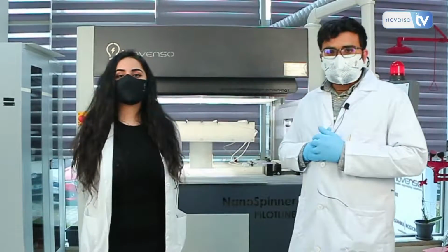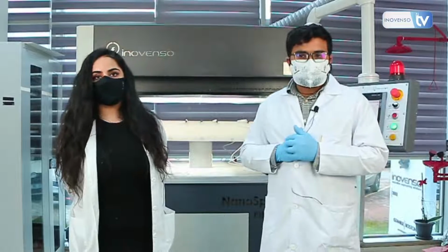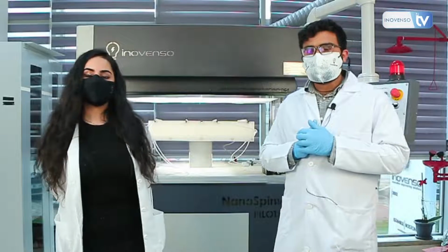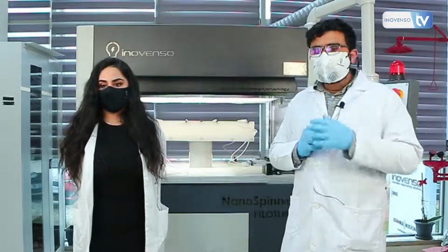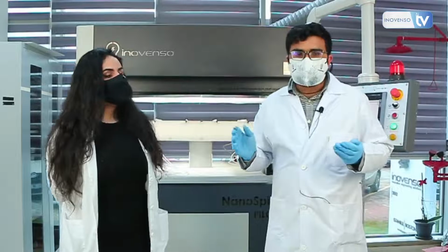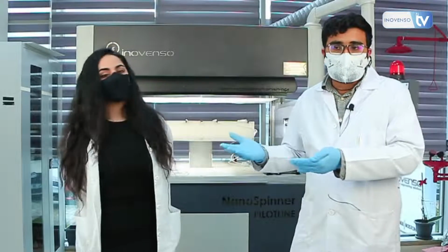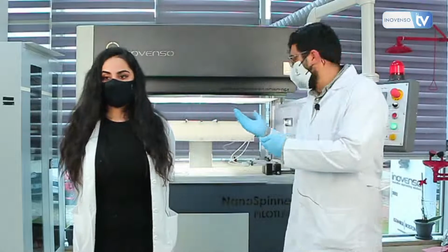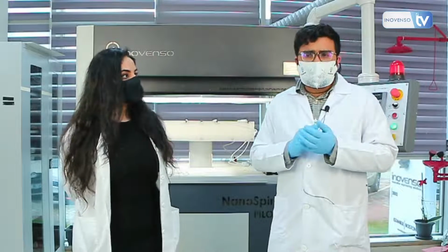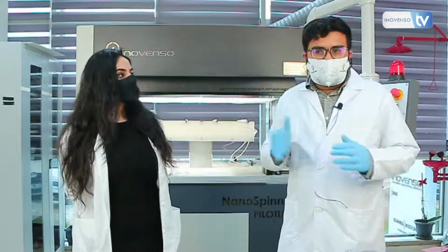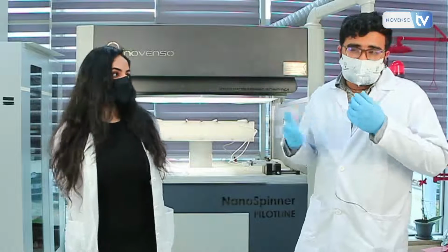Of course, it depends on the electrospinning unit types. If it's laboratory scale, it's less. However, for industrial and pilot, as my colleague mentioned, it's much higher. Right, because you have a large amount of solution, and you need to overcome that surface tension, so you need higher voltage as a result for the mass production devices. But for lab scales, when you're just dealing with a single needle based system or maybe multi-needle of small Taylor cones, you don't need that much charge or voltage to push it.